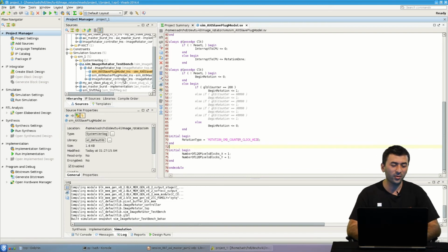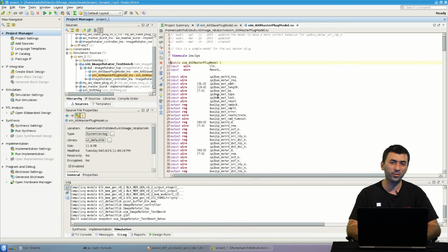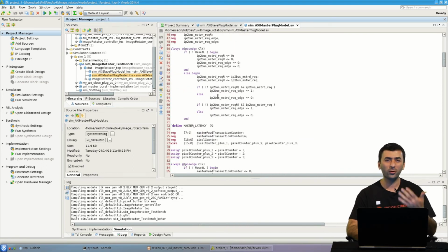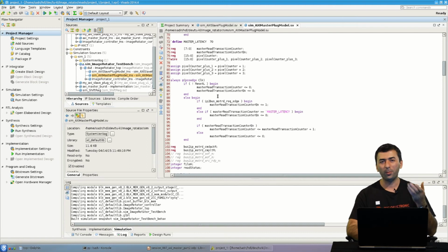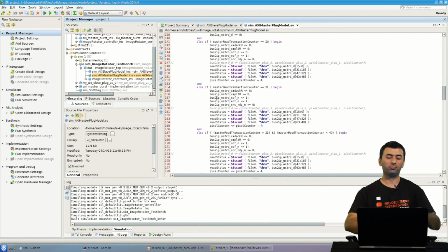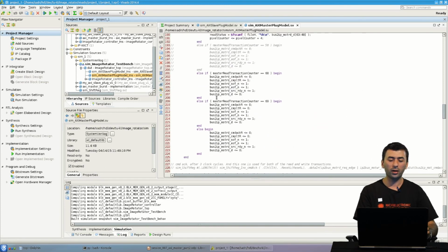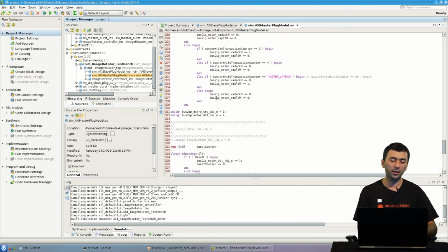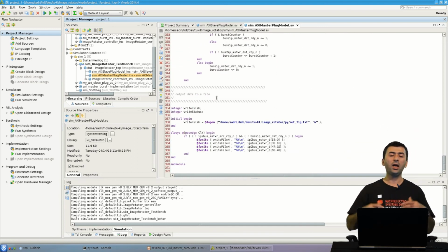And then there is the model for, in fact, the AXI Master IPIF block. It's kind of more complicated. It resembles the operation of an AXI Master Burst IPIF block. By looking at the Xilinx documentation and also by looking at the real operation of the interface between an AXI master and the AXI subsystem of ZYNQ, I have come into developing this module. It's not that complicated. It's not that simple. And I have tried to make it as accurate as possible.